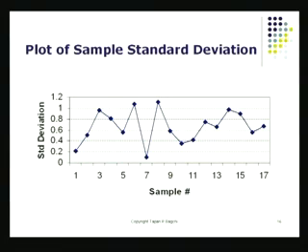I calculate a similar statistic called the range, which looks at the highest value in the data collected and the smallest value in the data collected within that sample. The difference between the highest value and the lowest value is what we call the range of the data, of the variation. This range actually is an indication of the consistency of the process. If the process is very consistent, the range is going to shrink down to pretty close to 0. But if the process has a lot of variation, range is going to expand. In some sense, this range is similar to what we call standard deviation, and we'll see that as we go into this theory here.